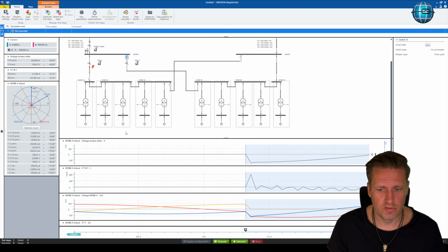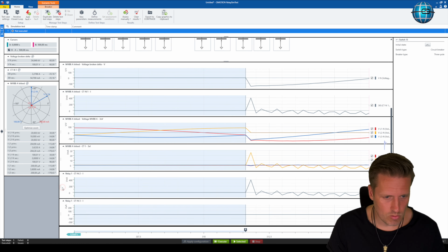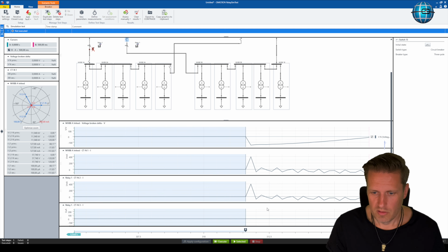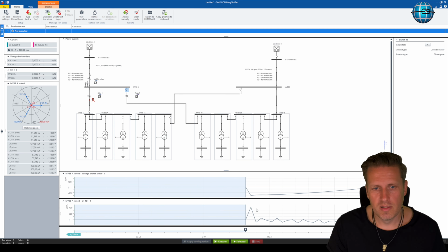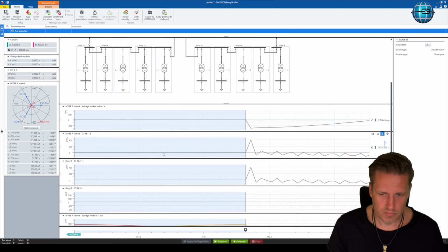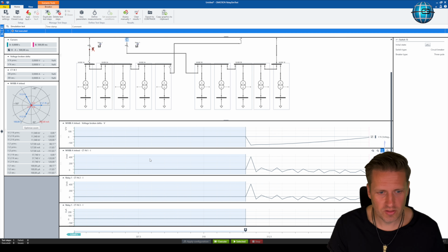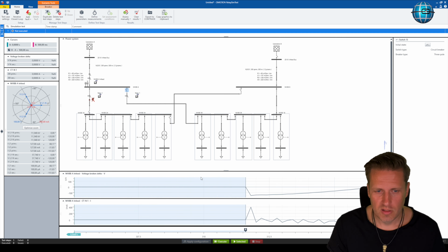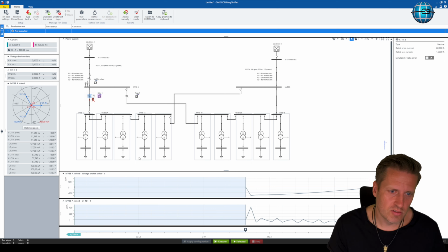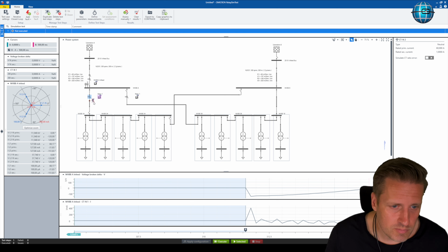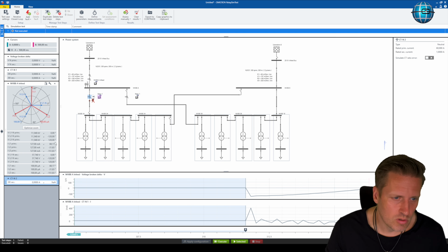Okay, so as you can see, we have now another split core relay here and another one here. Here where we see no signal, this is this one, of course. It's the 3 because the switch is opened. And we can see that both the in-feed here, this current transformer and this current transformer, have the same direction and the same amount. Probably it's a good idea to pin also this values that we can see it here.